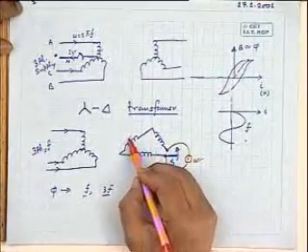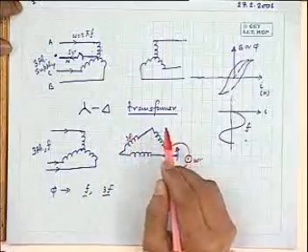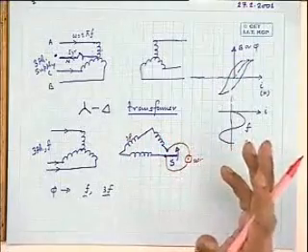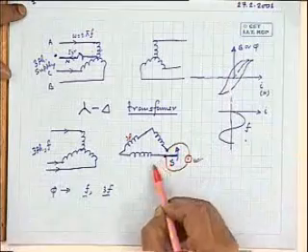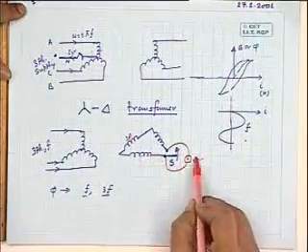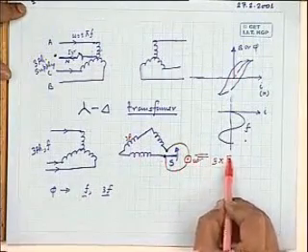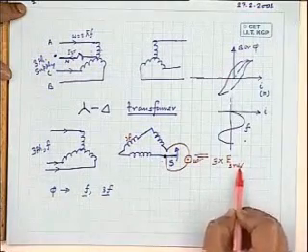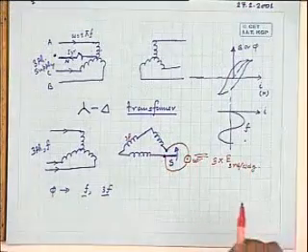But the third harmonic voltages, which will be induced in each of the windings of frequency 3F, what is the phase displacement between them? 0. They are co-phasal voltages. Therefore, the voltage here you will be getting 3 times the induced voltage, third harmonic induced voltage here. This will read 3 times the induced voltage, third harmonic, in each winding, per winding. This voltage will be induced.